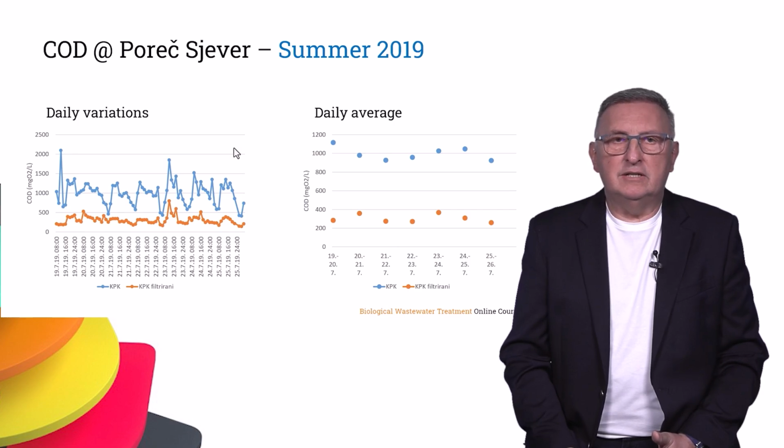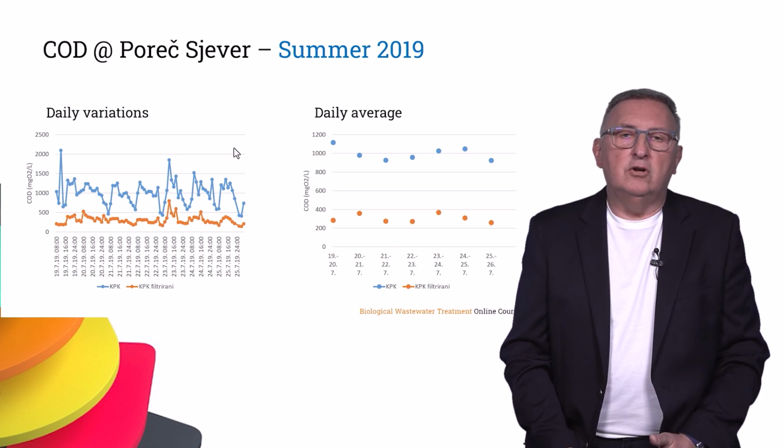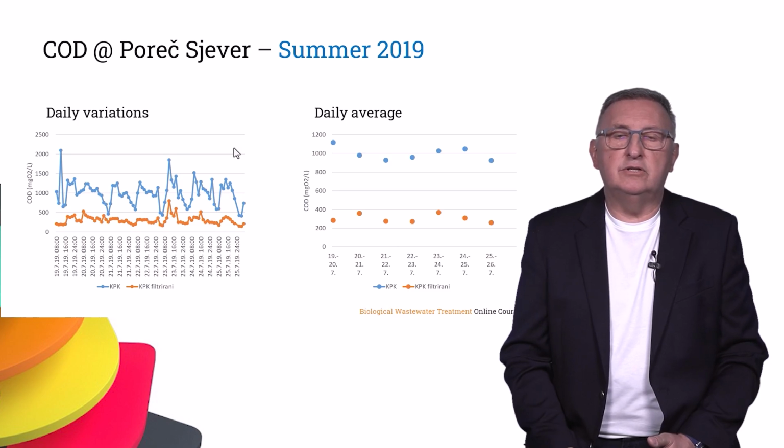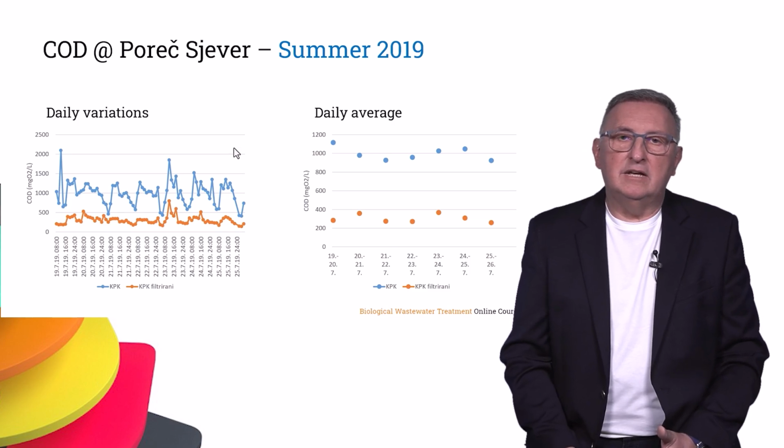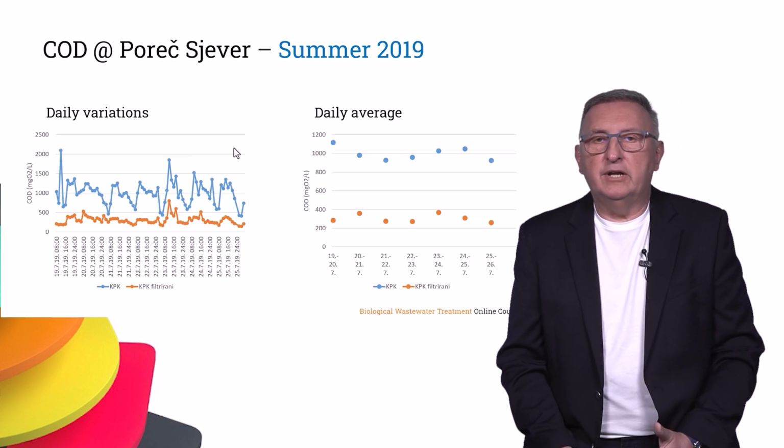And you can see also that the COD value is around 1,000 milligrams per liter, saying actually that this is quite concentrated sewage, and it's in summer conditions. So we have here a very little contribution from rain, and also the wastewater collection system is designed as mostly a separate sewage system, so sanitary sewage is treated separately from the rainwater system.